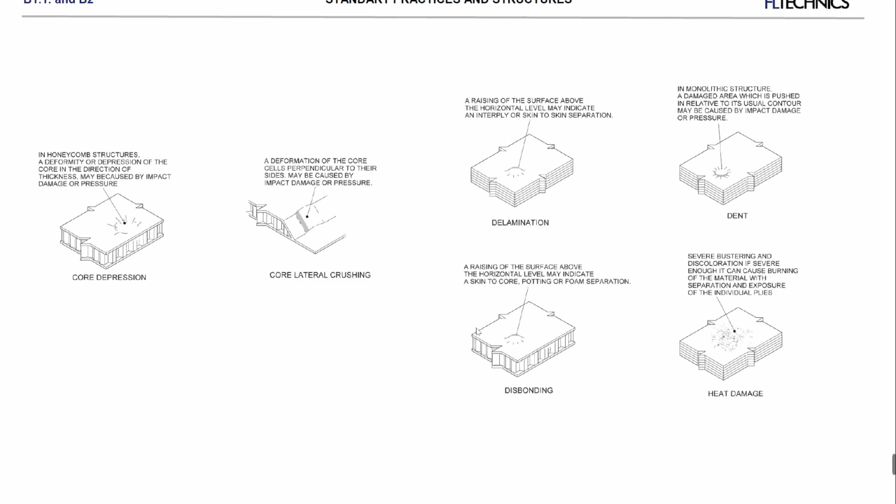But here I was talking mostly about some repairs that we do in a line maintenance environment, just easy repairs, where you have to apply paint or primer to protect the structure against corrosion, maybe to apply high-speed tape, because as I told you, when we talk about skin repairs or some other repairs, we need a professional for this, okay?